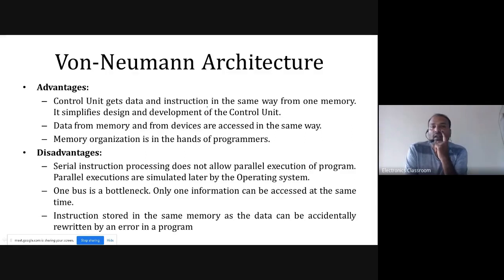The control unit gets data and instruction in the same way from one memory, since both data and code share the same memory. Which means if I want to read an instruction from memory, I need to follow the same process, and for data it will also follow the same process. So it simplifies the design and development of the control unit.